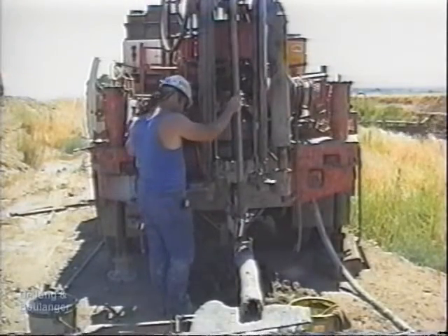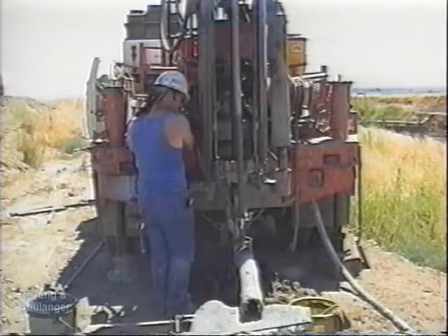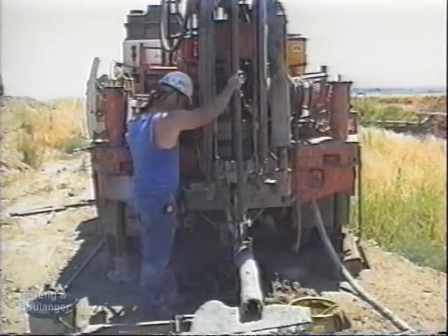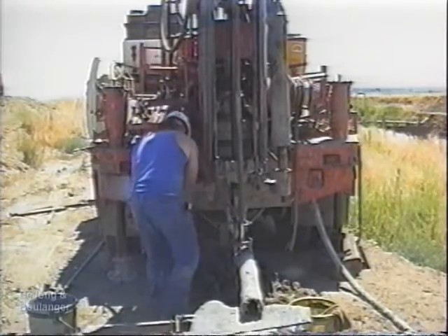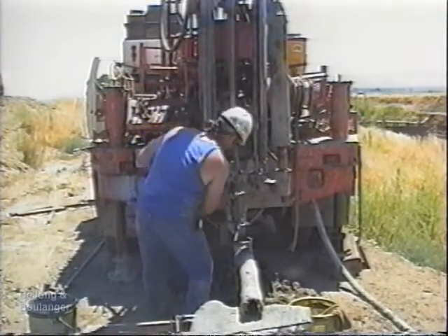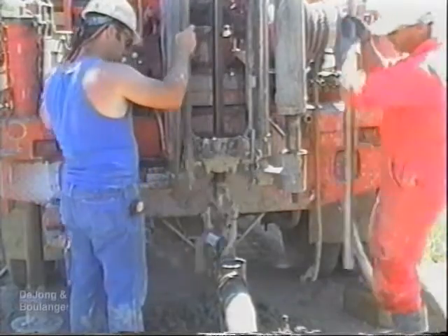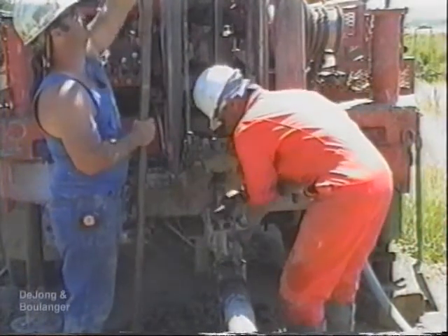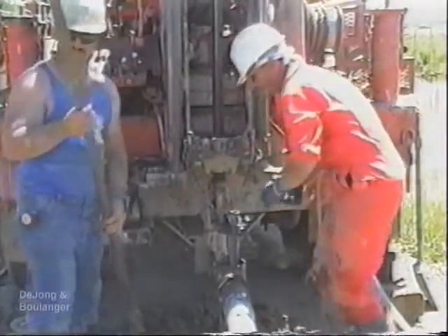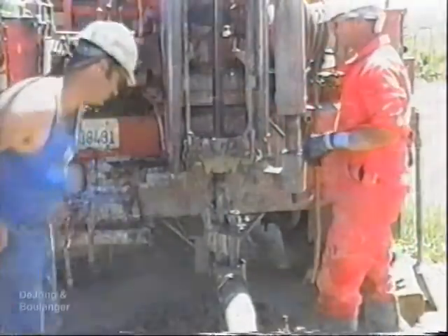Upon reaching a desired depth for sampling, the drill bit and rods are no longer advanced. After the mud has cleared all cuttings from the hole, the drill rods are withdrawn from the borehole and the lead rod and drill bit are disconnected. The sampler is then attached to the drill rods and lowered to the bottom of the hole. After sampling, the lead rod and bit are reconnected to the drill rods to continue drilling.